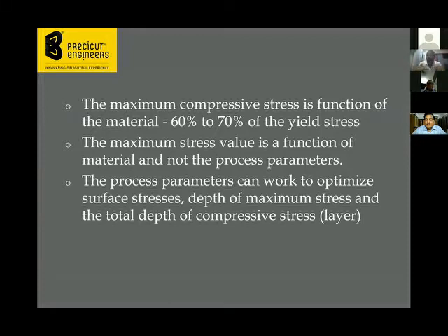We can achieve the desired depth of the stress, basically the depth or thickness of the layer, and the desired stress profile which is required. Beyond this, the machine cannot generate more compressive stress values. Beyond a certain point, all the energy is wasted and plastic deformation will start.